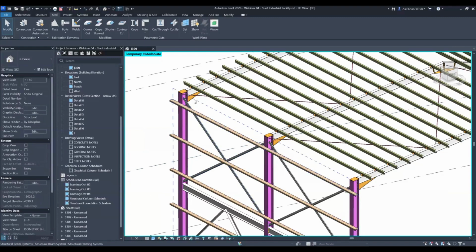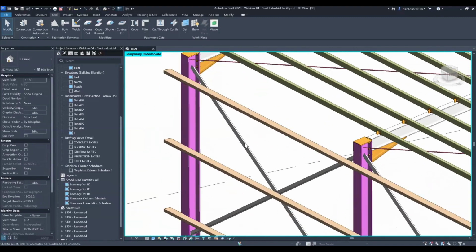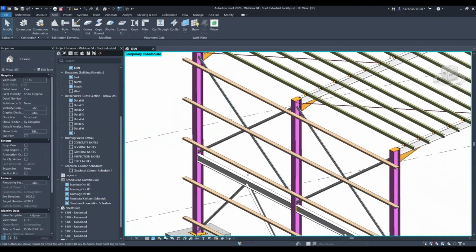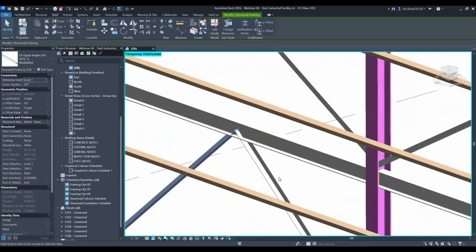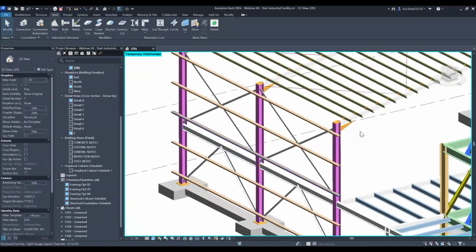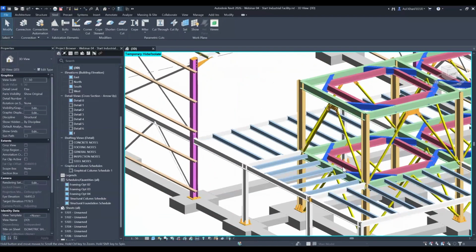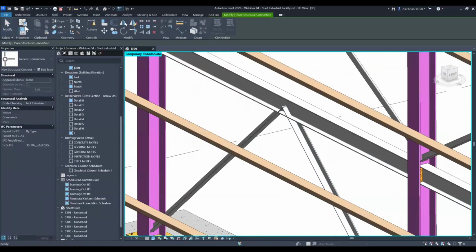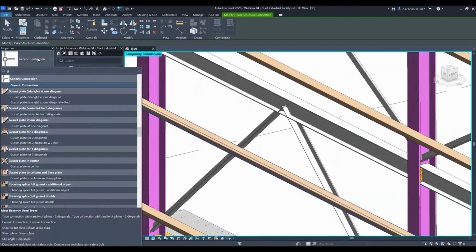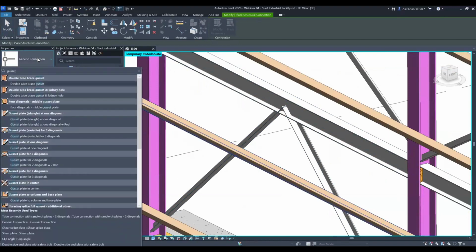I put some bracings, and now I'm going to show you how to put some bracing connection when it's angle connection, when the bracing members are angled, not like previously on this one. These were tube, but these are bracing right now. Okay, great. I'll go for the connection, and I'll choose a connection which is called gusset. Select the gusset, and there it is. My gusset connections are here.